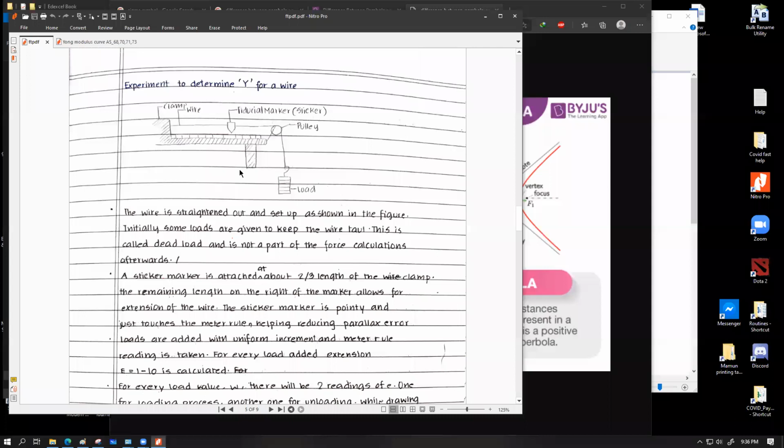And first, at the very beginning, you should finish up the experiment by tearing up the wire. You should do a destructive test for one specimen to find out exactly what is the last limit of this thing. Once you know that value, then you should design your experiment using values that are lower than that.